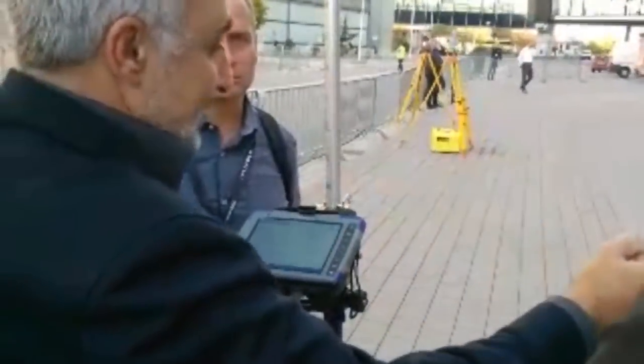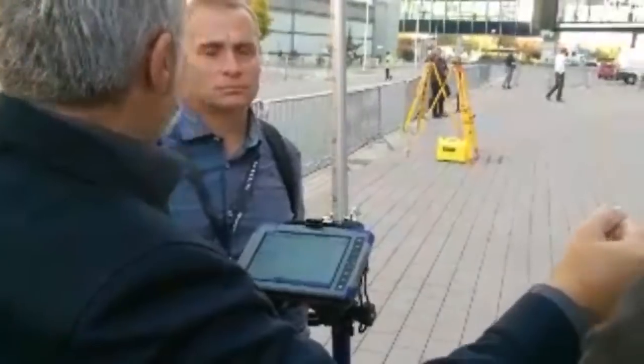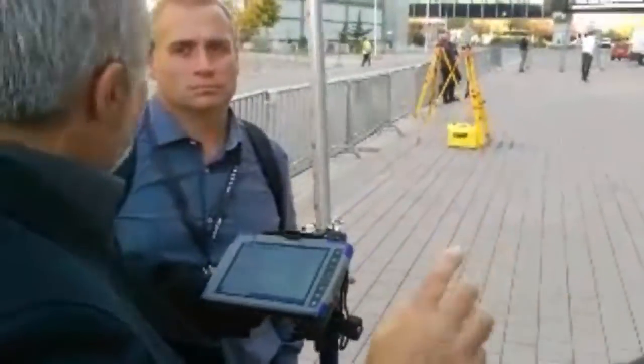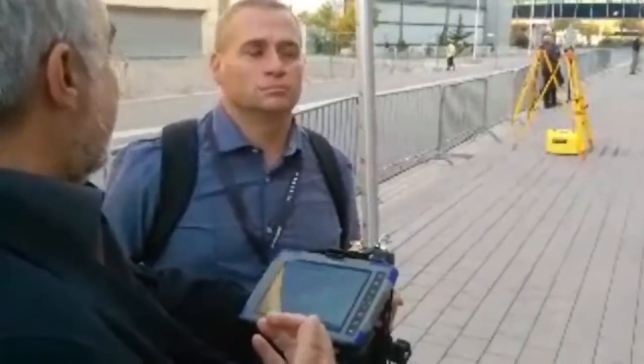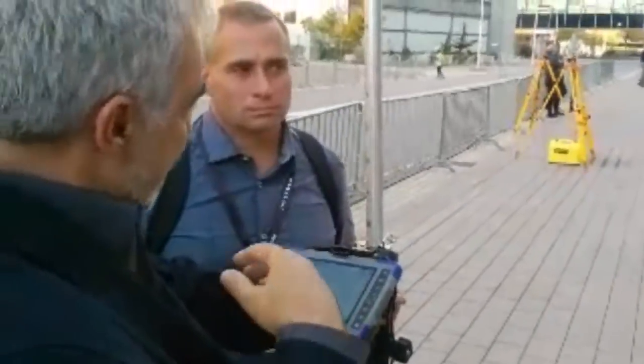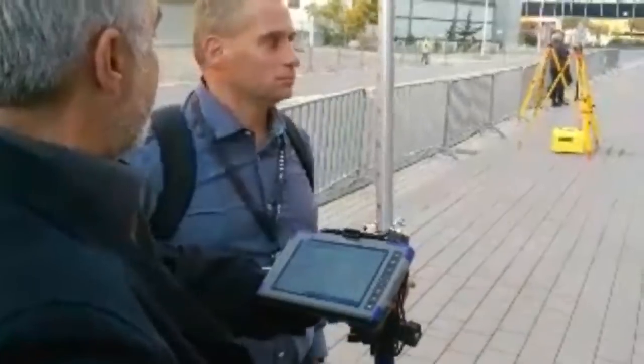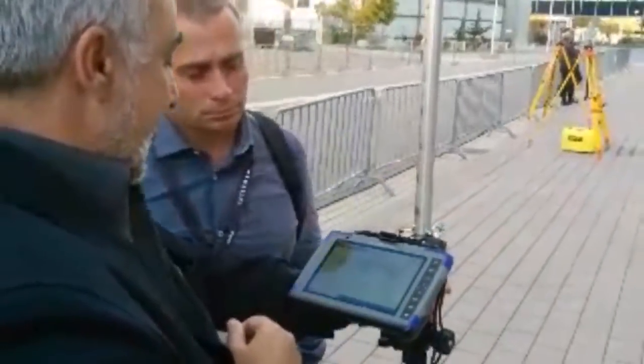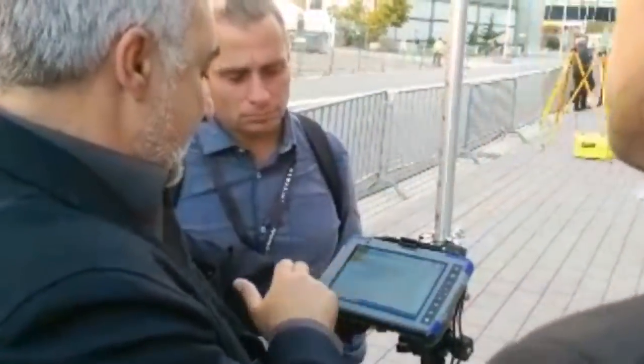Every time I take the point, I take the two coordinates, and after the third point, then I have a localization. But it's done internally. You don't need to care. It will be done internally, and we start working from the first point, right? So any coordinate system. So let's do the hybrid resection.